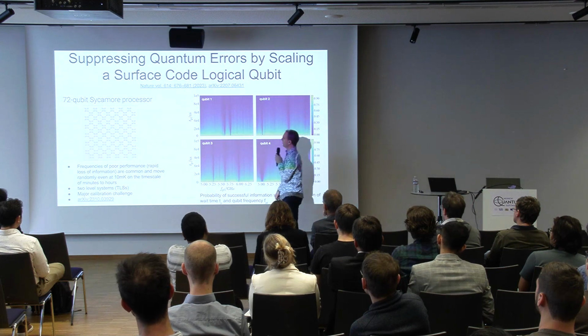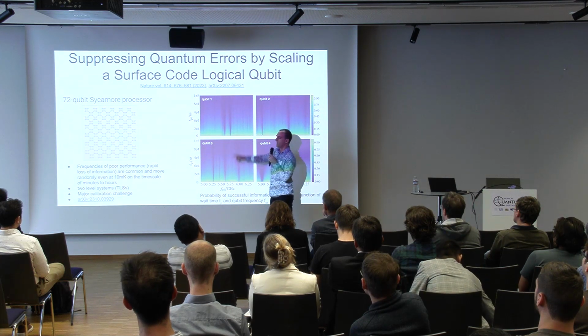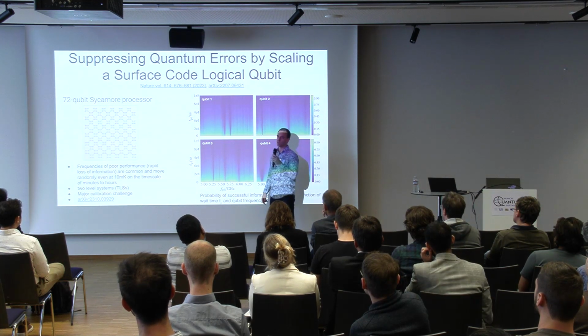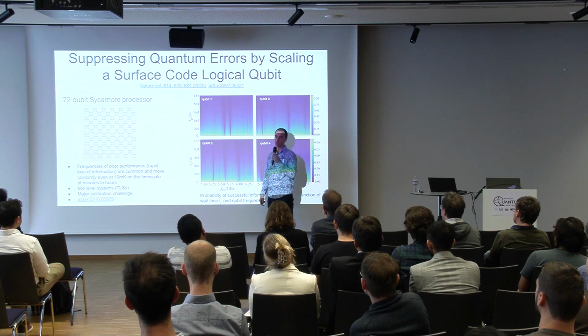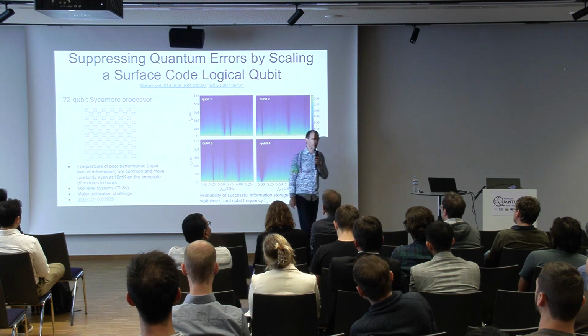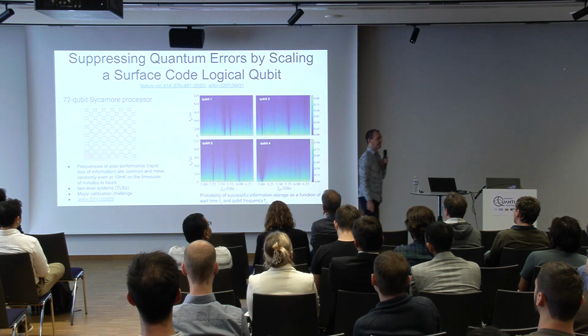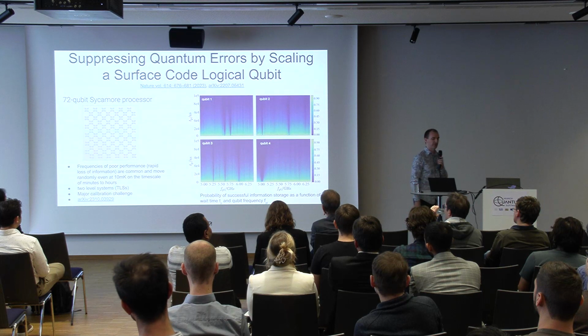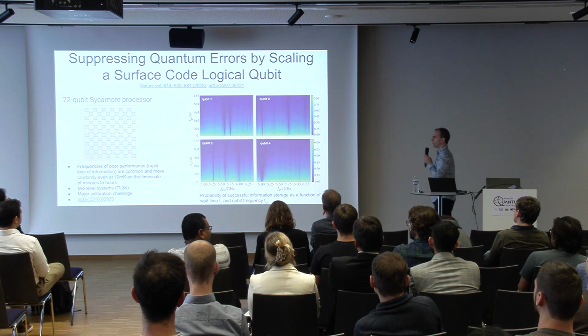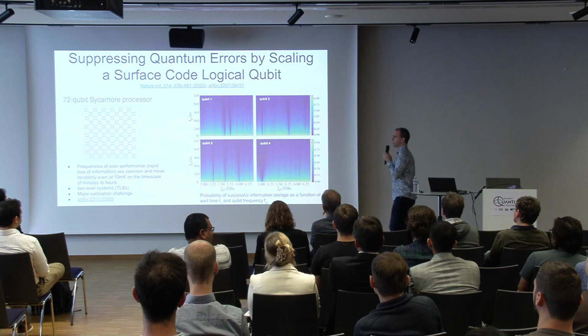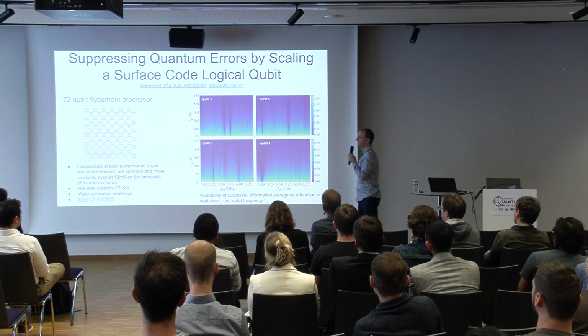So you'll tune up your qubit saying, all right, it works well here, and then you look away for a few minutes and come back and you go, it doesn't work well at that frequency anymore, and you have to tune up your computer again. Now, if you have a small number of qubits, this is okay. Once you start having dozens of qubits, it becomes a very large software engineering problem to try to remember the frequencies where it worked out, remember the configurations where things worked out, and keep everything working consistently.